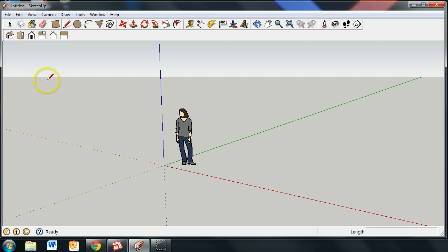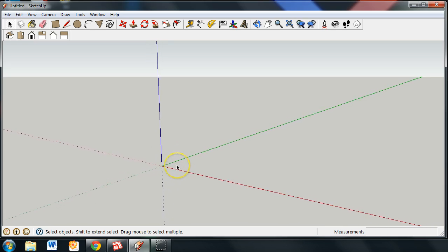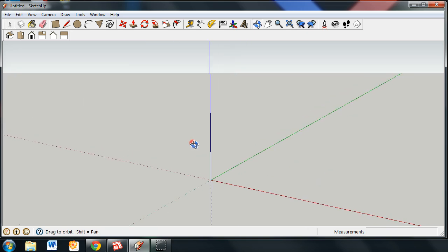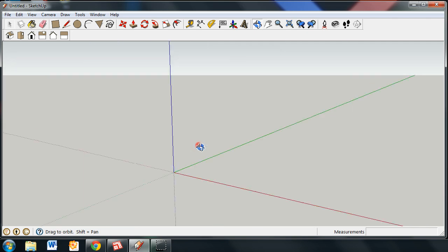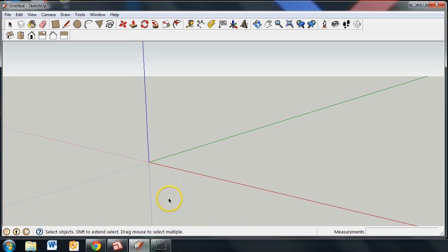So in SketchUp, to get started here, we need to make sure that we take the mouse pointer tool, click on the lady, and delete her. She's gone. After she has disappeared from the window, you're then going to be able to see that you can zoom in and zoom out using the wheel of the mouse. You can also orbit by pressing on the wheel of the mouse and moving the mouse left and right, front and back. Okay, that's going to help you in viewing options.